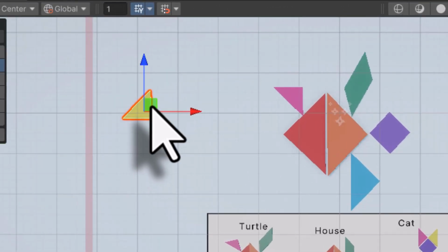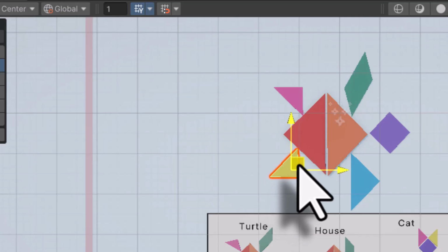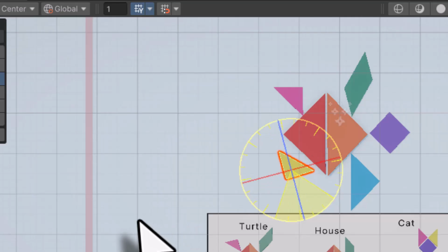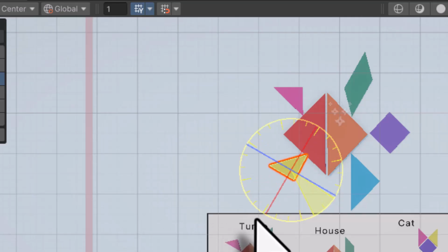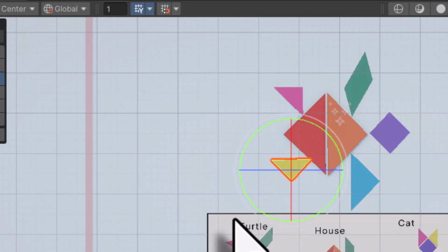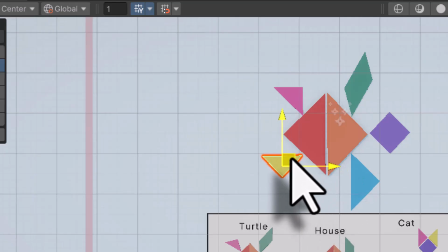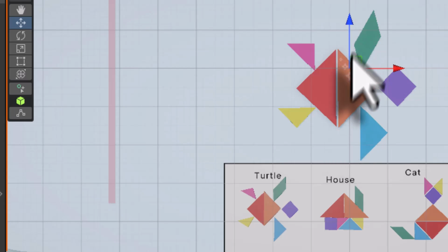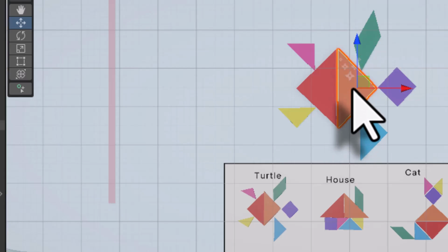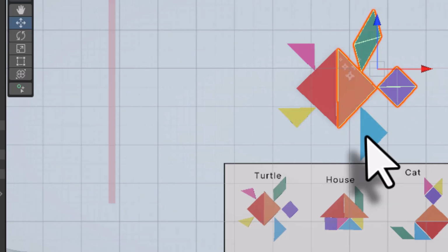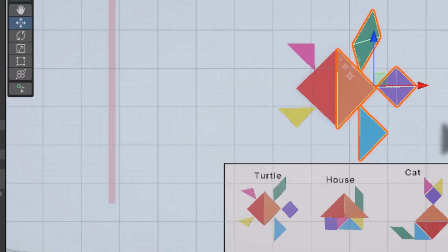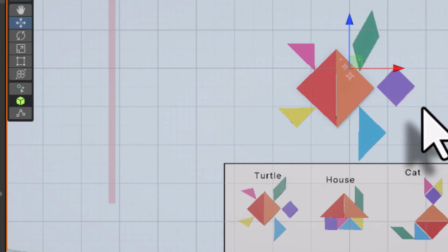So in this mode now, I will drag this and keep this here, press E, Control pressed and drag to left to rotate this. I will set an angle something like this, press W, drag it and place it correctly, and now we have our turtle ready. So I will just select. For multiple selection, you can hold shift and select multiple objects like this, and I will just pull it and place it precisely like this. So now we have our turtle ready.